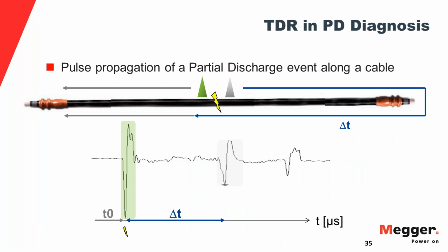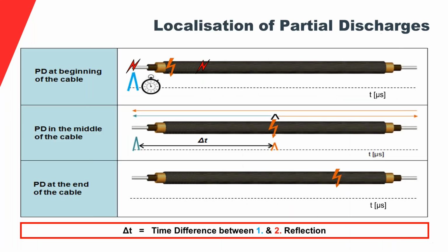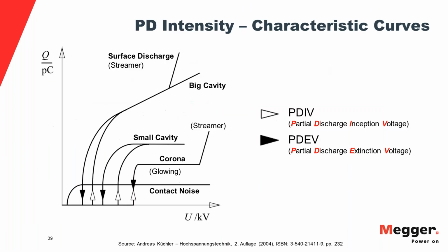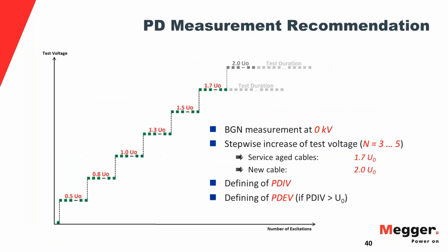And then you save that trace, and the software will use this as its gold standard for the measurement to discriminate against. So any pulse that comes in will be judged against that calibration pulse that you recorded earlier on. And then you do a background noise measurement.